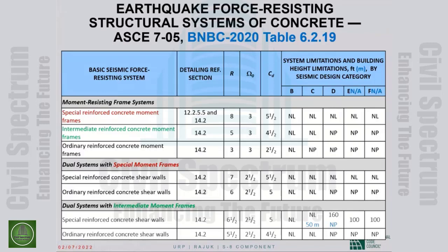there are height limits on almost all structural systems, with the exception of special moment frames of concrete and steel and dual systems utilizing special moment frames. Those are the only systems without height limits on them. Every other system has height limit on it, and most of the time the height limits are in the higher design categories, not so much on B. Design categories E and F, I have mentioned repeatedly, do not exist in Bangladesh.